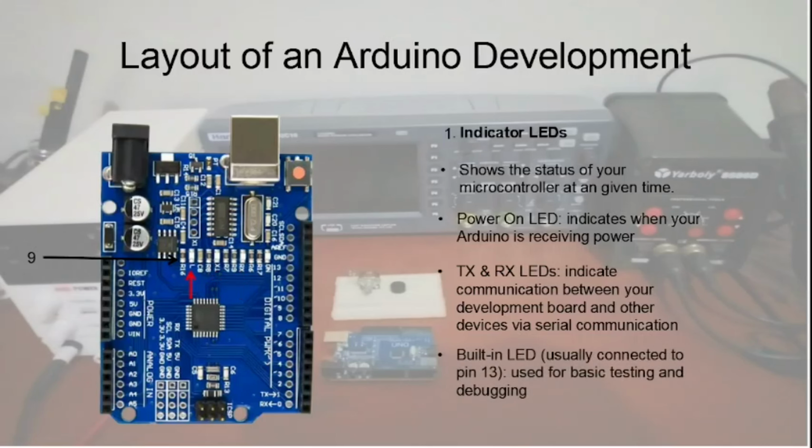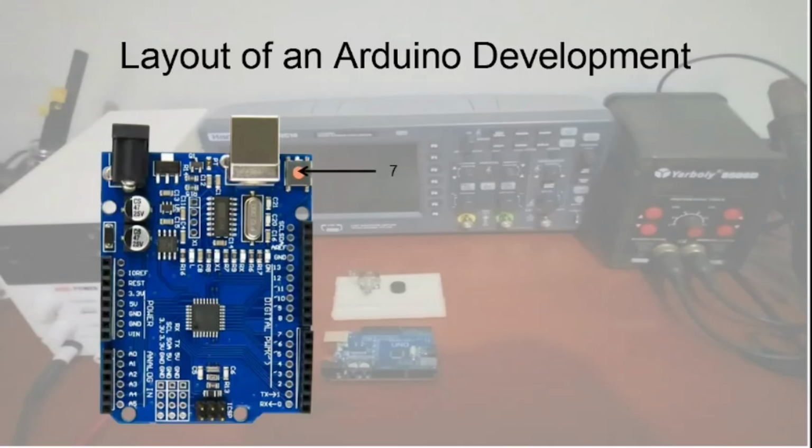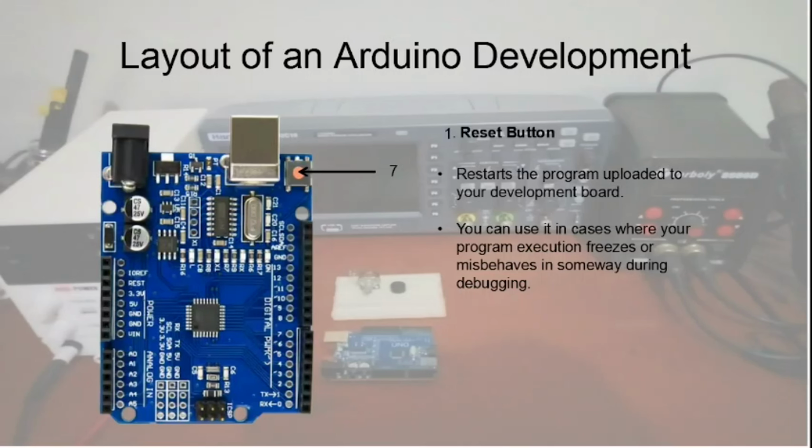Finally, we'll look at the reset button. Pressing the reset button restarts the program that's currently being run on your development board. The reset button essentially has the same effect as unplugging and replugging your development board. You can use it in cases where your program execution freezes or misbehaves in some way during debugging.